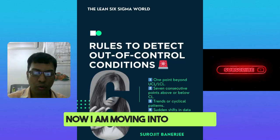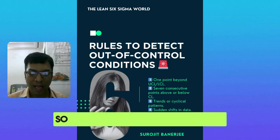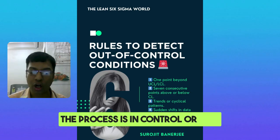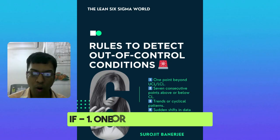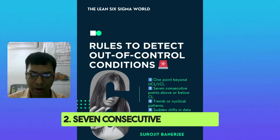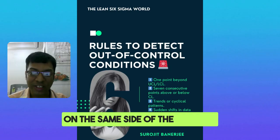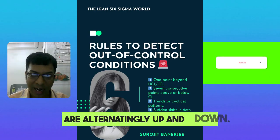Now I am moving into the rules to detect the out of control conditions. So I am going to explain here 7 different points which are important to understand to know whether the process is in control or not. A process is said to be out of control if one or more data points fall outside the control limits. 7 consecutive data points are increasing or decreasing in nature. 8 consecutive data points are on the same side of the average. 14 consecutive data points are alternatingly up and down.